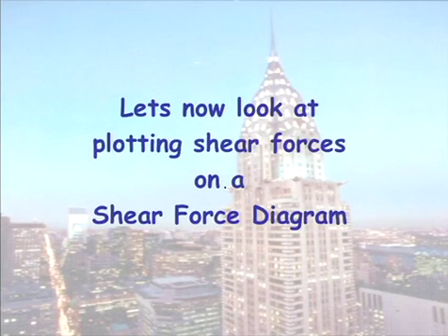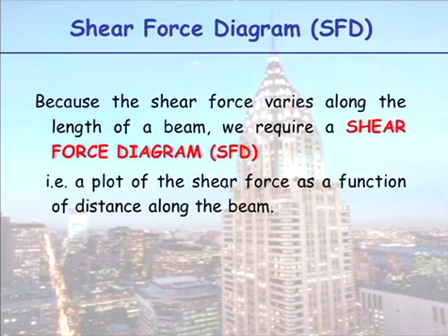I need to draw a diagram of the bending moment, the value of the bending moment all along the beam. And since I'm doing the bending moment, I may as well draw a diagram of the value of the shear force all along the beam. And we call these shear force diagrams and bending moment diagrams. Shear forces being the easier thing, we'll start looking how to draw a shear force diagram. So, as I've just said, the shear force varies along the length of the beam. So we require a plot of the shear force along the length of the beam, which we call the shear force diagram.